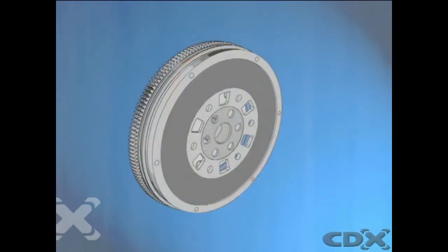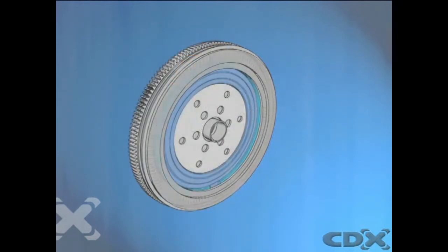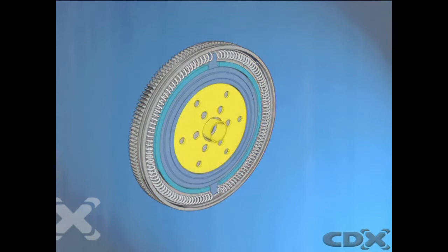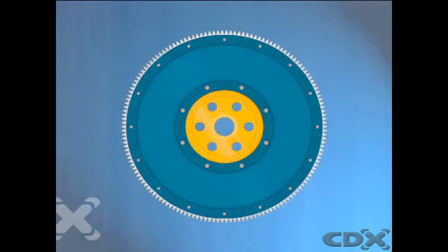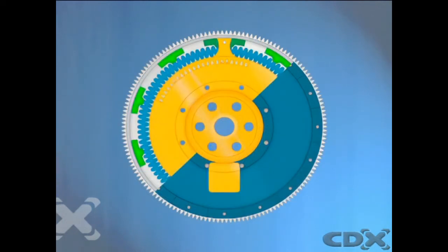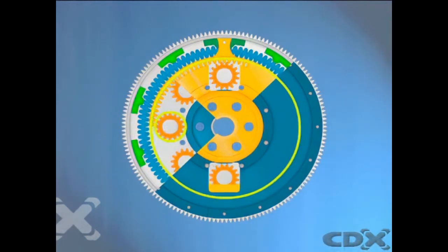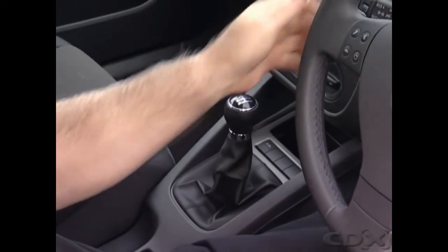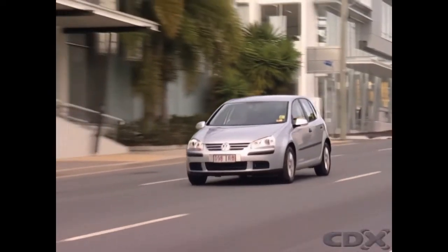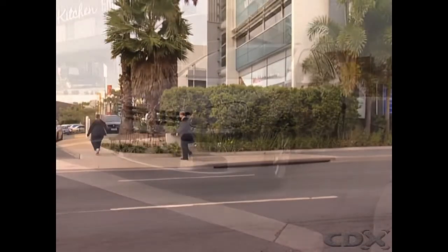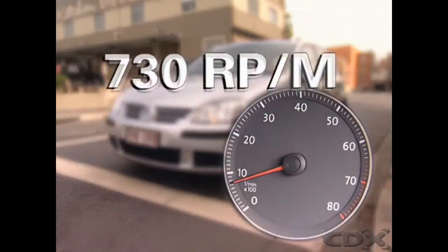The system also has a center support bearing that carries the load between the inner and outer flywheel and is fitted with damper springs to absorb shocks. The second type of DMF incorporates planetary gearing. It's designed for engines with stronger vibrations in the lower RPM range. As well as greater driving and shifting comfort, the planetary DMF provides the benefit of lower fuel consumption because the idling RPM is lower.